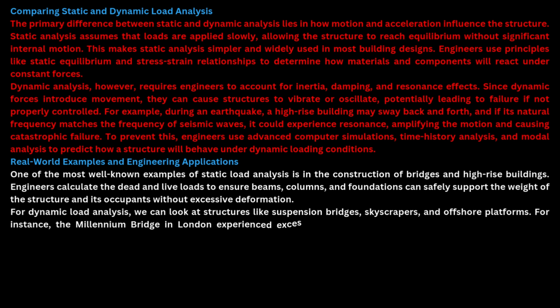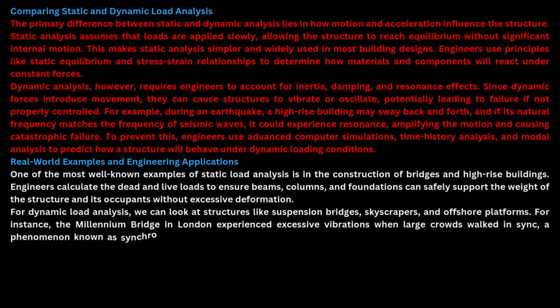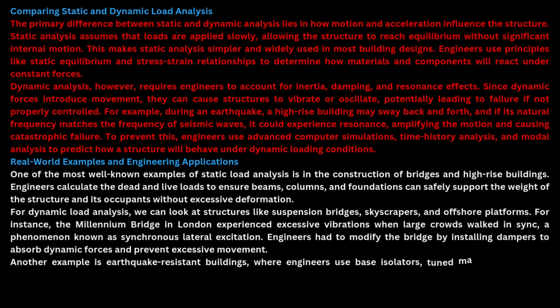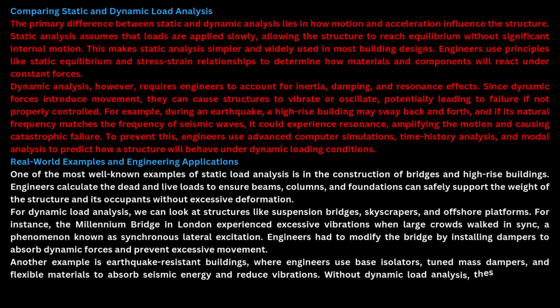For instance, the Millennium Bridge in London experienced excessive vibrations when large crowds walked in sync, a phenomenon known as synchronous lateral excitation. Engineers had to modify the bridge by installing dampers to absorb dynamic forces and prevent excessive movement. Another example is earthquake-resistant buildings, where engineers use base isolators, tuned mass dampers, and flexible materials to absorb seismic energy and reduce vibrations. Without dynamic load analysis, these structures would be at high risk of collapse during strong earthquakes.